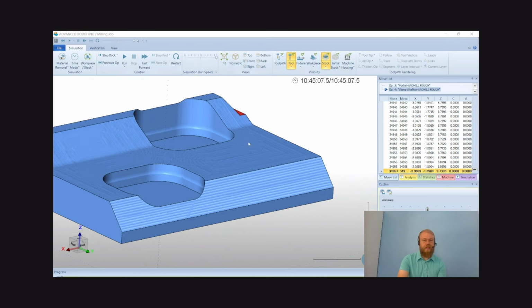So that's pretty good. The steep shallow, other than the tool not being long enough on the ends there, it will follow along the side walls if we need to, cut that to size, and will follow along any tapered walls and any flat areas with an equidistant tool path to give us a better surface finish there.